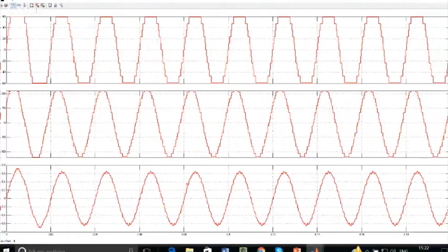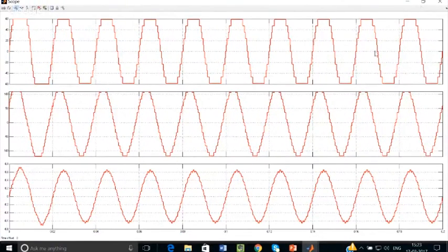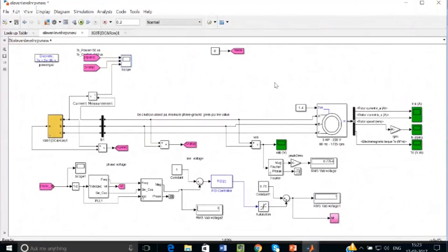And the current waveform is also shown here. So now we want to find what is the THD. Our main aim is that THD should be less than 5%. Okay, that's why we have gone till 11. So there, I already told you why we are using power GUI, because all these THD analysis can be done here. So I'm just clicking on this power GUI block.